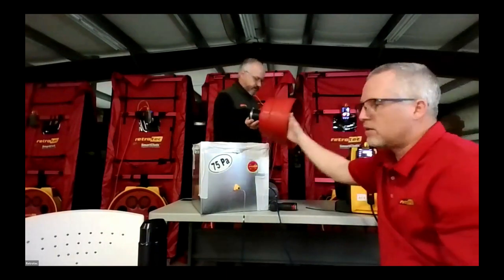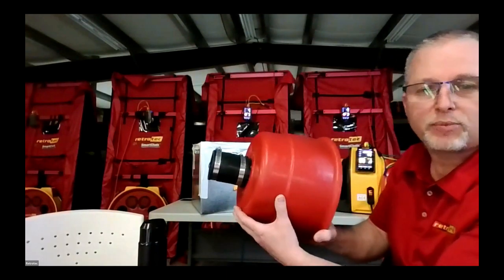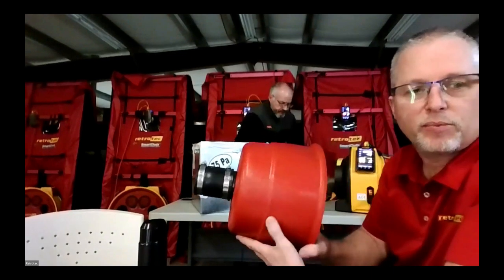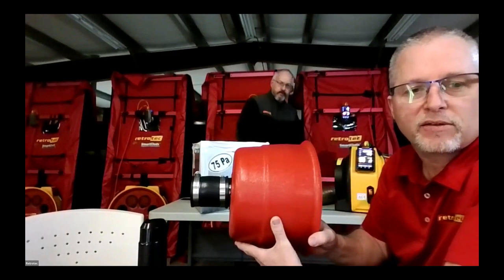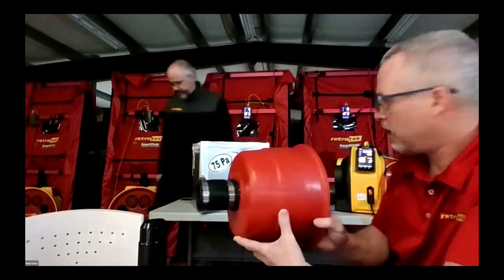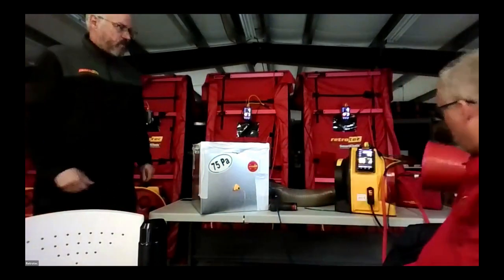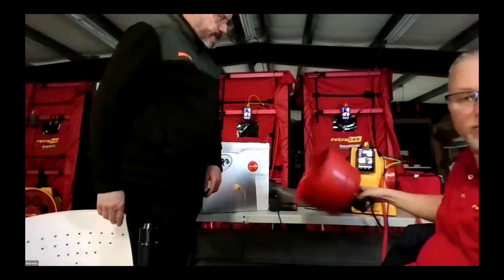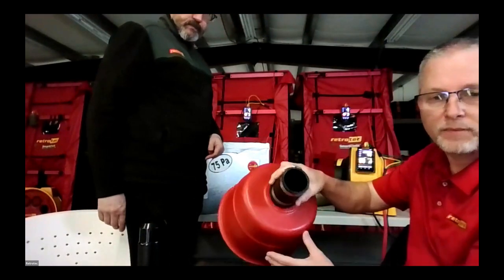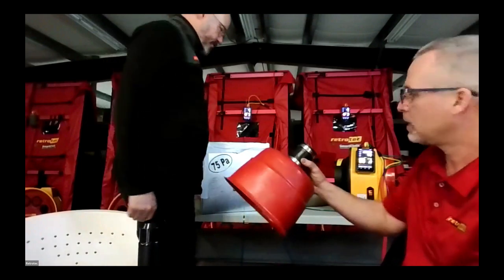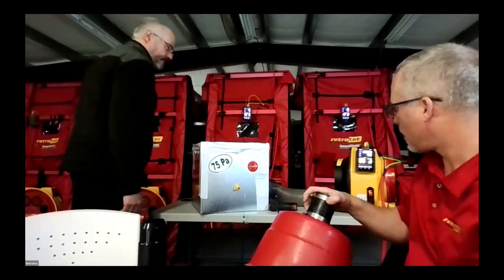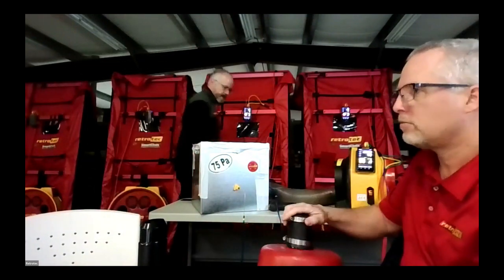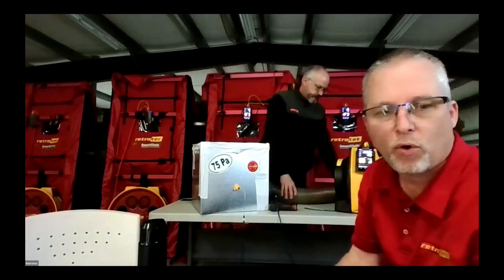And about the depressurize function, this is so you can depressurize the duct system. Like I said, if you pull negative pressure on a duct, you can check for leaks that way with the smoke. It connects on the inlet of the fan, and then the flex duct connects to the collar so you can depressurize. If you need more flow,